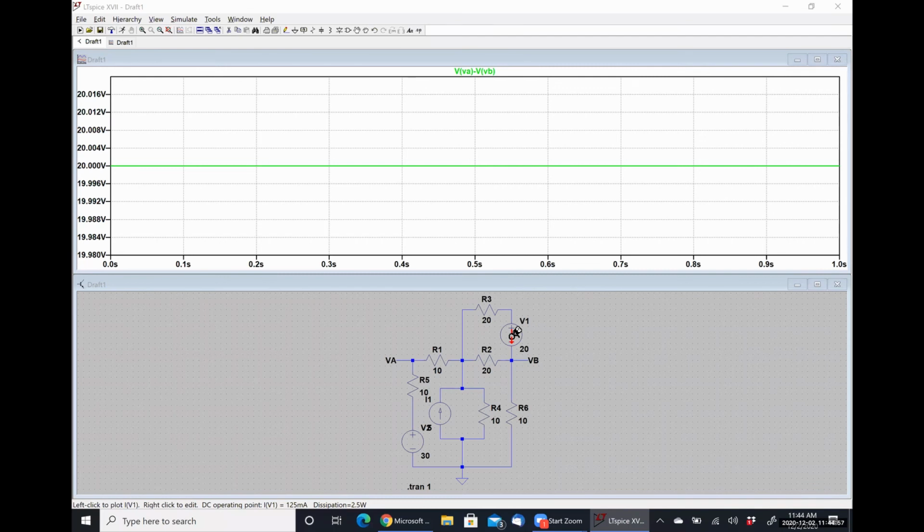Anyway, if I mouse over a circuit element, I get a current probe that tells me the direction of current flow that's considered positive. If I mouse over a node, I get a voltage probe. If I click here, it gives me the voltage at this particular node, and it's telling me right here that this is node 2. Those are the different tools you have in a transient analysis. It doesn't give you the power, although if you wanted the power, you could simply multiply the voltage and current waveforms and get it. Pretty easy, right?